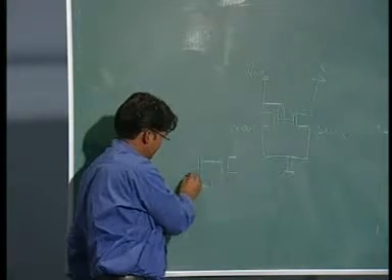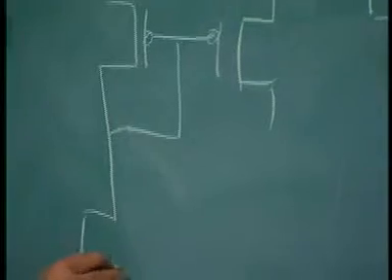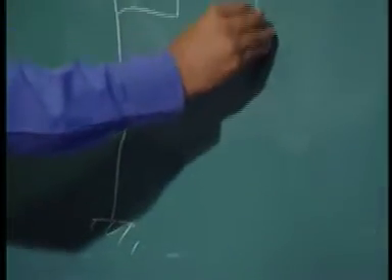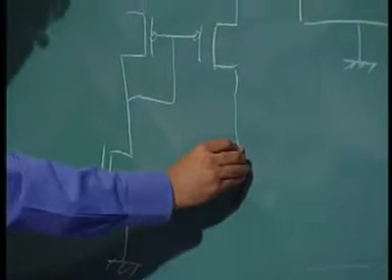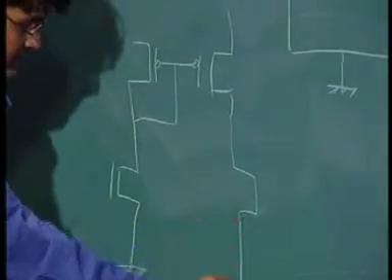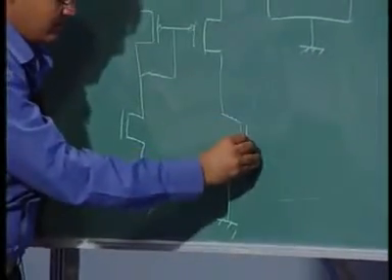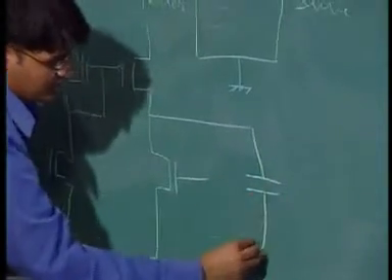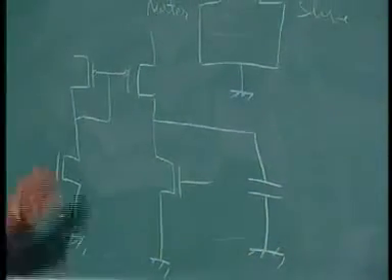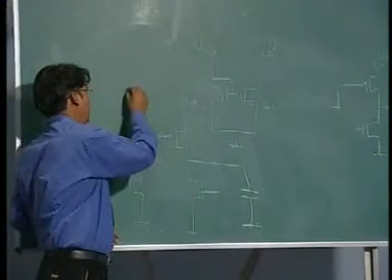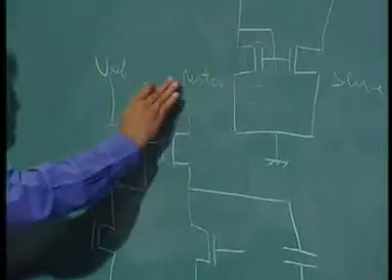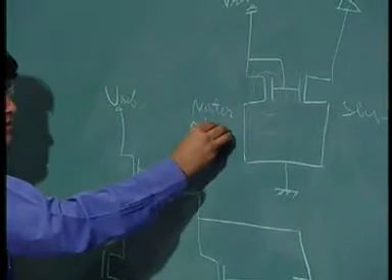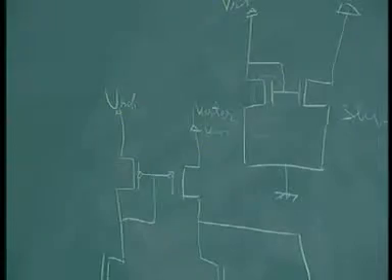And just common this one, and there you require one NMOS, just ground this one, and then you require another one, ground this one. Here I will apply some load. This is a simple differential amplifier. Here I will apply V reference, this is the master, and here I will apply the V vary. I will explain this one because this will be better.